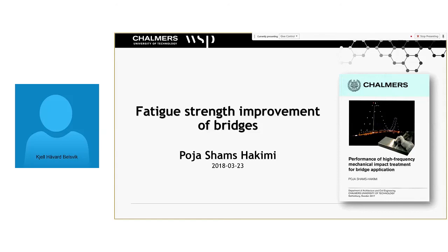Well, to be conservative, maybe 10%, as the top side of the bridge girder is not totally subjected to fatigue either, as we have some pedestrian areas and areas that are not subjected to traffic on the top flange as well.